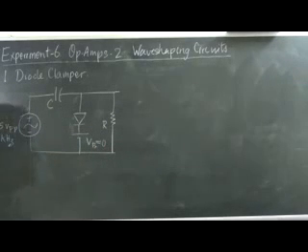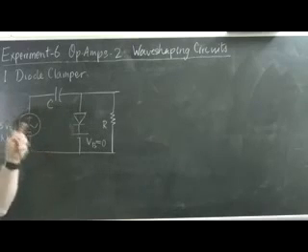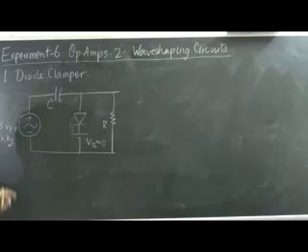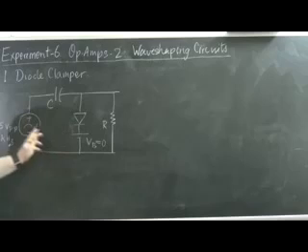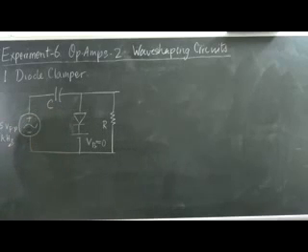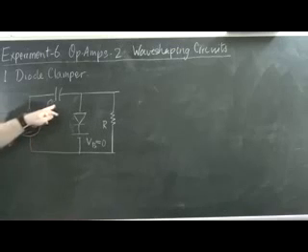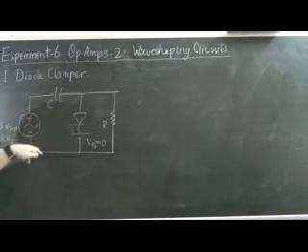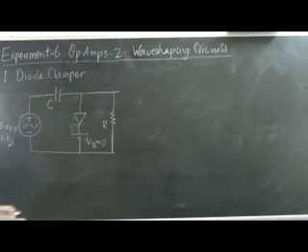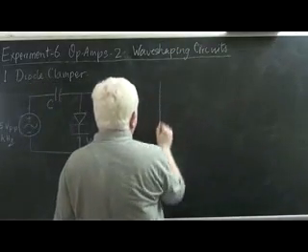So initially, current will flow through the capacitor and cause it to charge. The capacitor is now being charged through a circuit of almost zero resistance. The only resistance that is present is the minor internal resistance of the source here, and the forward resistance of the diode. So the capacitor voltage more or less stays in pace with the supply voltage, and hence this terminal is equal and opposite to this terminal, and the output remains 0. So let's just plot the input versus the output.